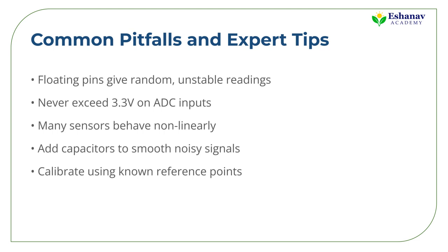Also, noisy USB supplies can spoil readings. Adding a capacitor across your voltage divider often smooths this out. Debug systematically. Start with raw ADC values, then layer on voltage conversion, and finally map to units. That hierarchy keeps problems easy to isolate.